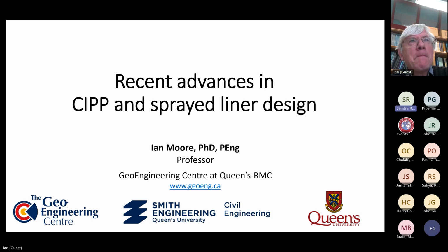Hi, John. And he says, great results for design of CIPP liners to resist joint opening displacements in the host pipe, but do you have any plans to extend the analysis to consider the impact of an initial annular gap between the liner and the host, as typically occurs at least in non-pressure sewer applications? Very good. Thanks, John. John is a CIPP guru and understands a lot about CIPP liners, and I've learned a lot of this stuff actually from John.